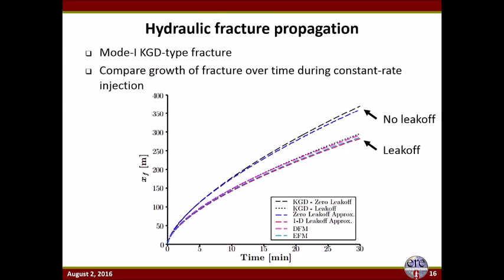Okay, so the last example I want to show you is a hydraulic fracturing problem. This just looks at propagation of a single mode 1 KGD type fracture. So the fracture has a fixed height, and we're interested in understanding how the length of the fracture evolves over time during constant rate injection. And again, we compared against the discrete fracture model and several semi-analytical models and found an overall good agreement.